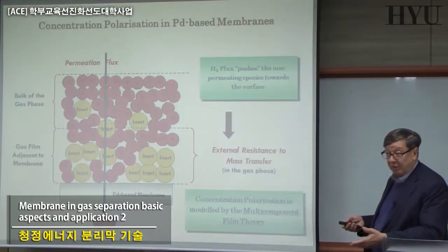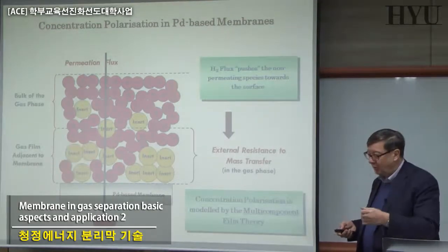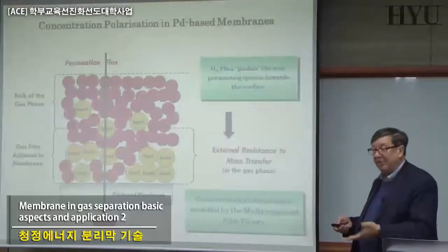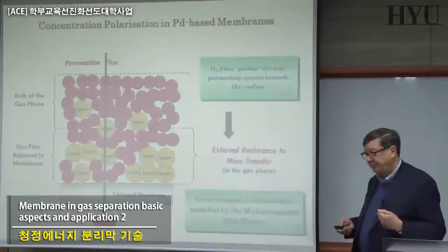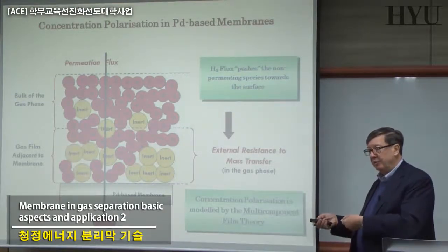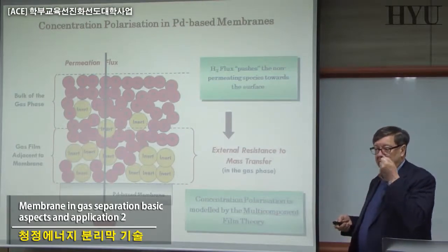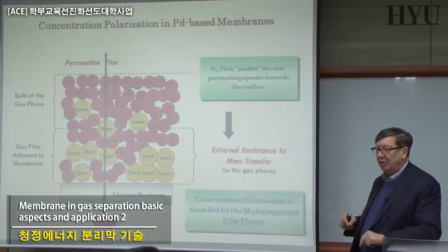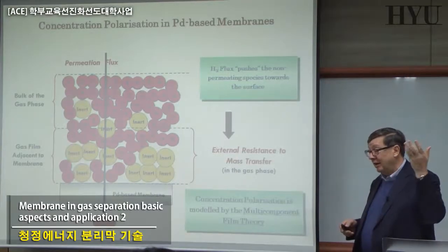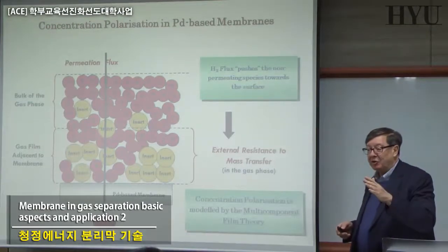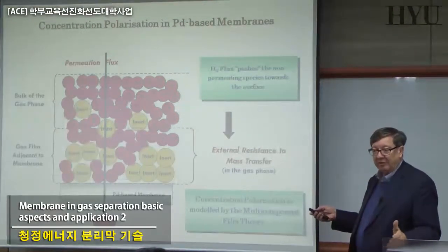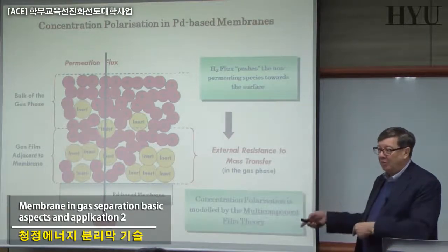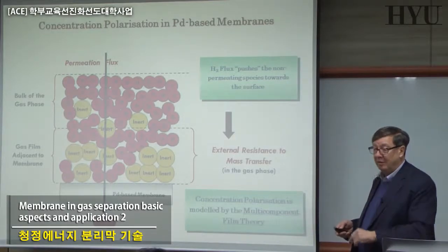That means what can happen, for example, in this case, if it's dead-end flow, if you don't have a high cross flow, you are increasing the concentration at the interface of the feed present in the solution. So you are increasing the osmotic pressure, which is related to the concentration through the van 't Hoff equation, and if you don't increase the hydrostatic pressure, the effective pressure, the driving force, is decreasing and decreasing to the point that what is going through the membrane is exactly what is present.